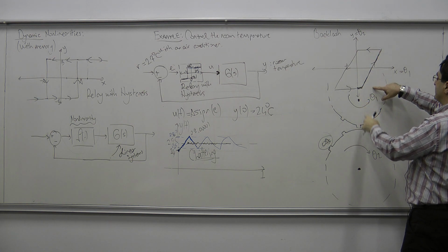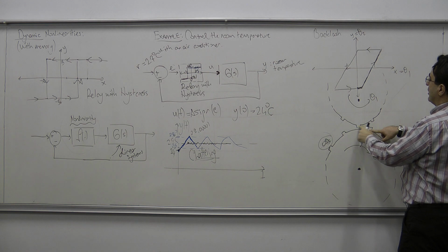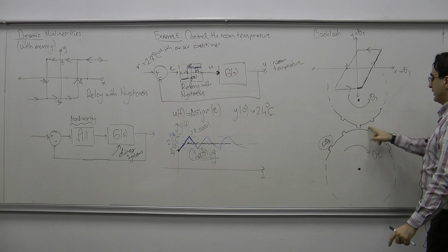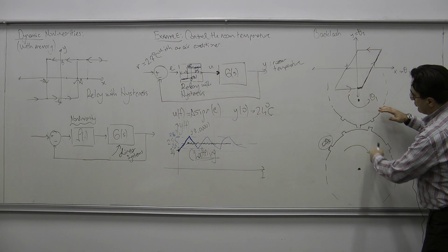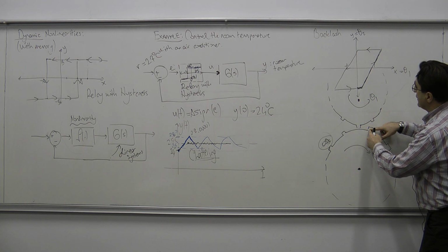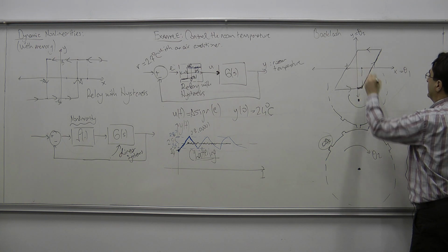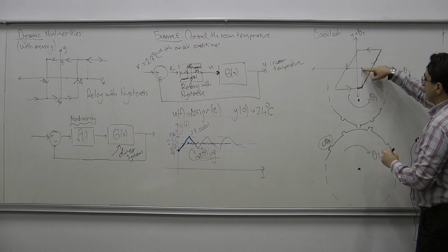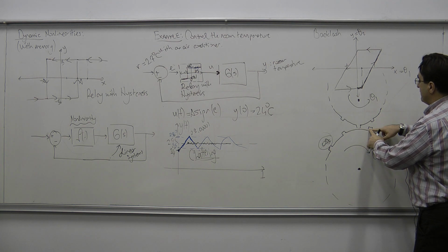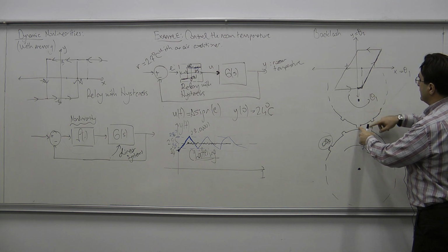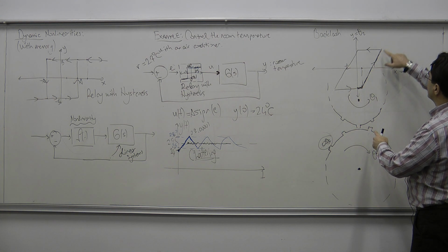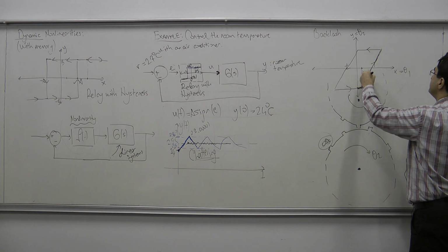As θ1 increases, as long as these two cogs are touching each other, we're going to have an increase in θ2. So this is going to start moving after these two cogs touch each other. This touching point is here. This is what θ1 should be when these two cogs start touching each other. And after they start touching, increasing θ1 is going to increase θ2, like this.